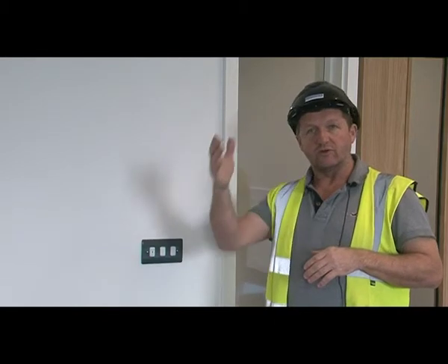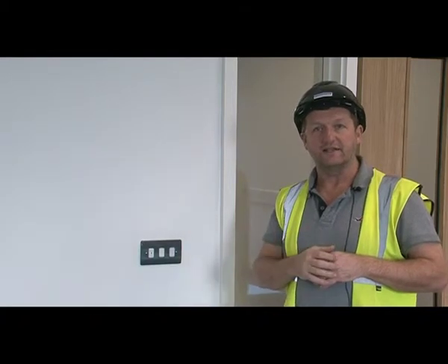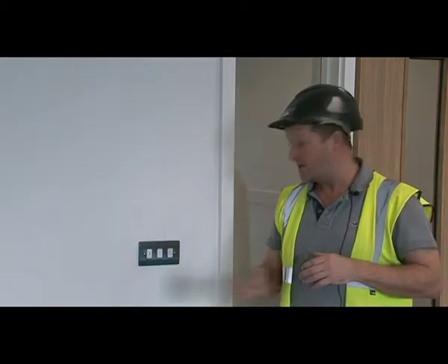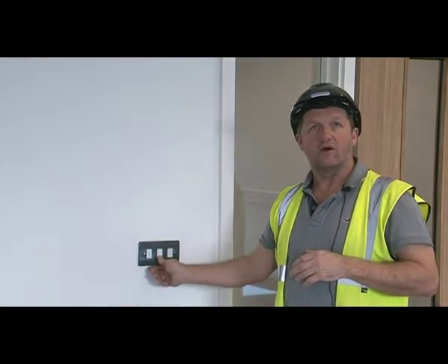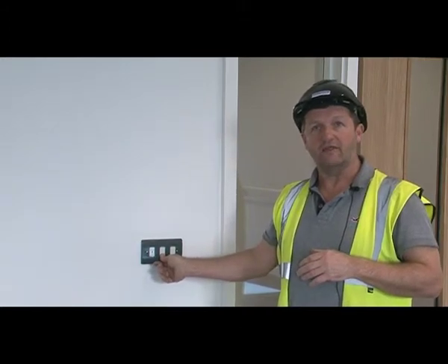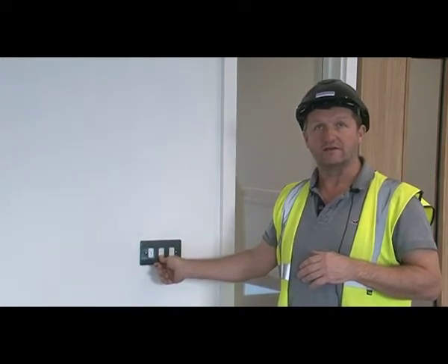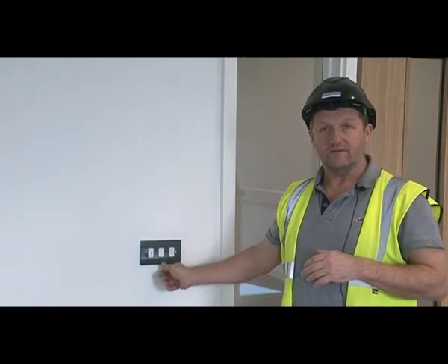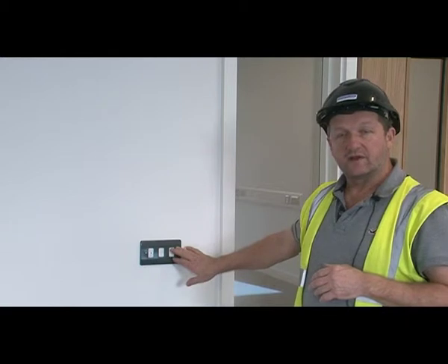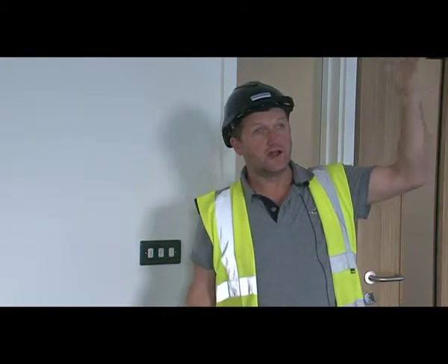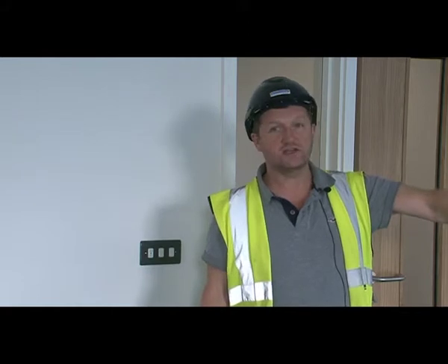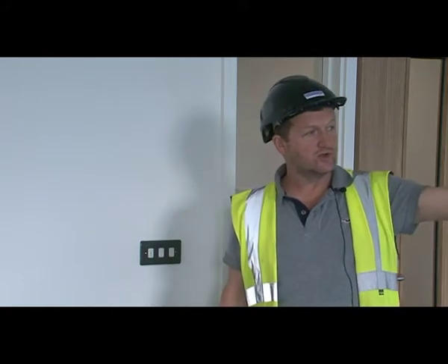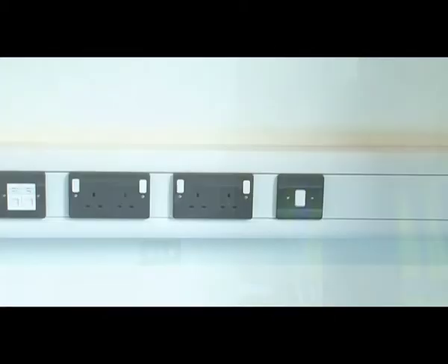In the corner of the room, which I'll explain in a minute, is an absence detector and daylight sensing device. So the two lights at the window will dim automatically. If you want to raise them lights, simply hold them down again and the first two will come up to full brightness and stay there. The second switch is for the teacher's wall, and that turns that one row off where the teacher is teaching. It's also got its own switch on the dado which can be operated from either the teacher's wall or as you enter the room.